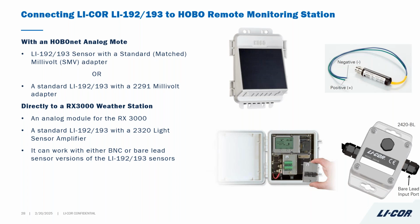We have millivolt adapters that change the current signal into a millivolt signal. So we have a standard millivolt adapter that's standardized to the specific sensor that it's matched to. So it'll give you a 0 to 10 millivolt output.